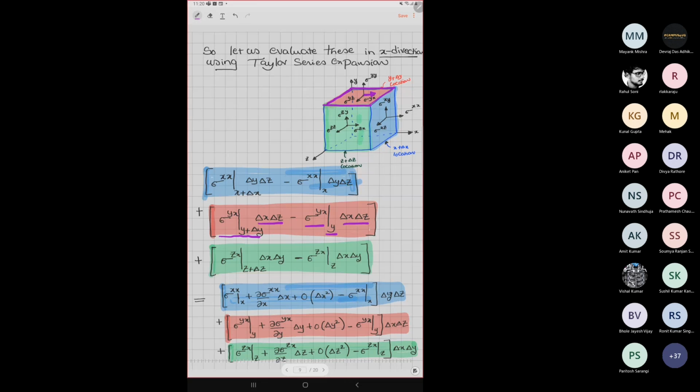These are the forces acting at two different levels, and what I am trying to calculate is what is acting across that element. We have written sigma yx at y plus delta y minus sigma yx at y, multiplied by delta x delta z, as the force acting on the surfaces passing through the material. That difference is acting.